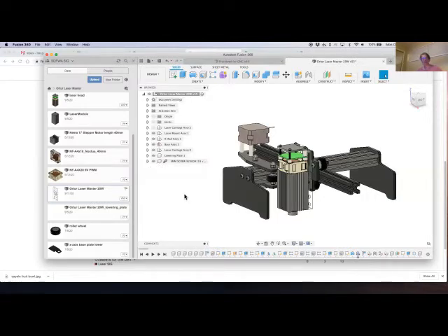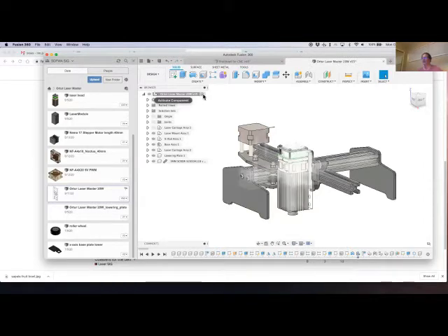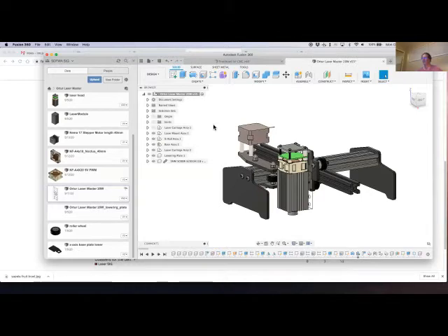So you have to tell, in this case, Fusion 360, what level you're making a change to. Are you making a change to a specific component, to its sub-assembly that it's in, or to the top level assembly? And the way that we designate that is called activation. So we activate the component for work. So right now the top level is active. So whatever I create or make at this point will be relevant to the top level.